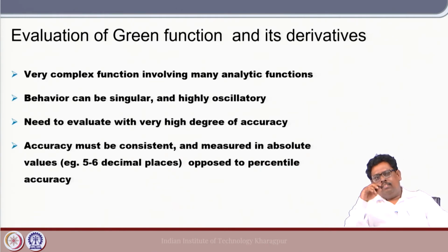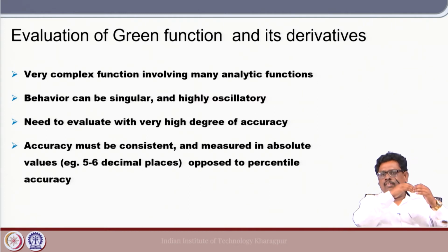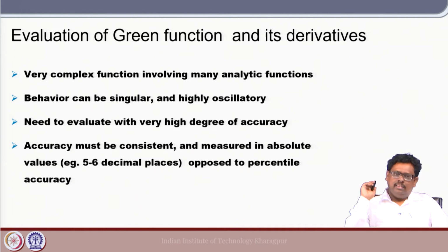So, now these are the key things that one must understand. First, this is a very complex function involving many analytic functions, right. Second, this behavior can be singular, especially when the field point equals the source point, and also when the panels are close to the free surface, the solution becomes highly oscillatory. And third, we need to evaluate the Green's function very accurately.